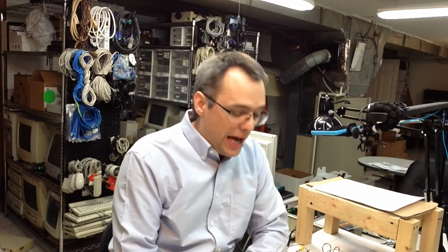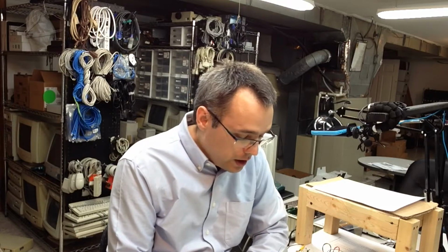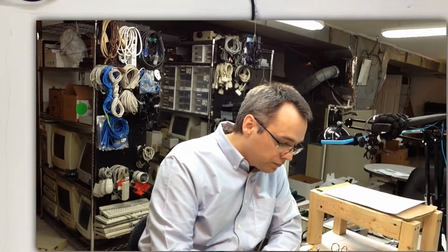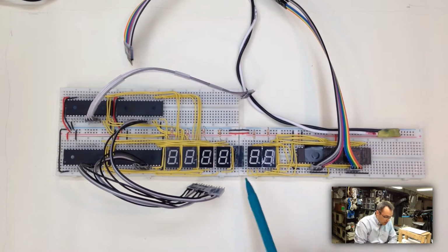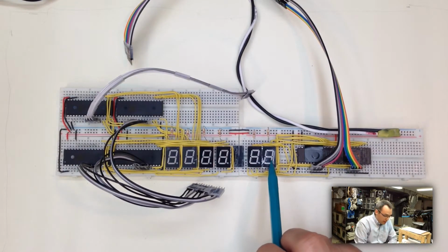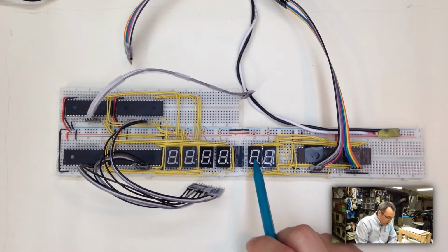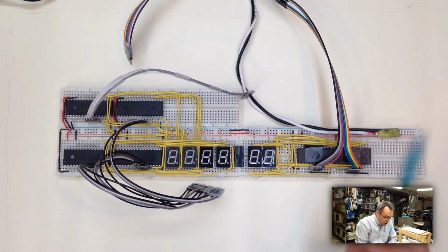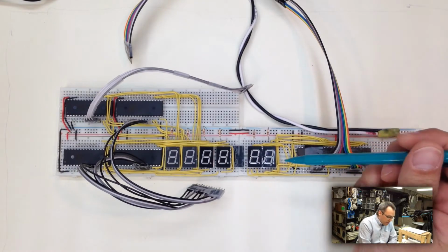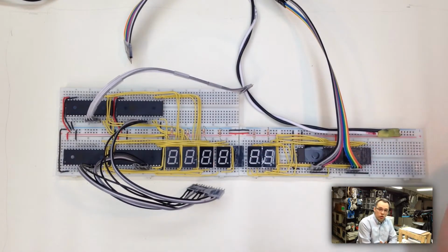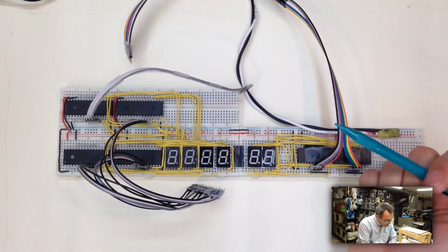Since we saw you last, I made a little bit of a change to that decoder, so let's take a look at that. What I did basically is I added an extra module to the decoder here to show the data bus, the 8 bits of the data bus. Just a couple extra modules here, a couple more ROMs, wired up basically identically to this, so there's no real change in the schematic other than it's a larger device now. It has 6 pieces instead of 4.